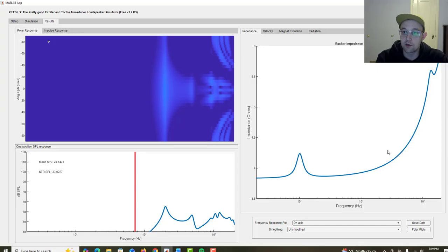So there's no modes showing up in here because the impedance peaks due to the modes are proportional to the velocity of the mode. Up here at high frequencies, the velocities are pretty much non-existent relative to this impedance, or the velocities are so small that we don't see anything due to them. So this is essentially the impedance of that exciter stuck to a giant block of concrete.